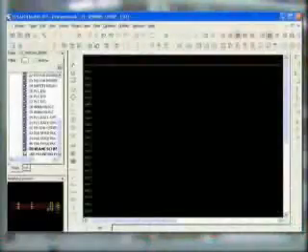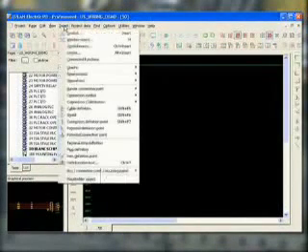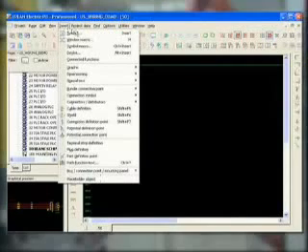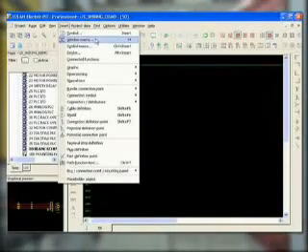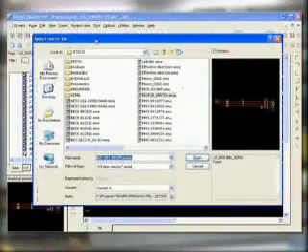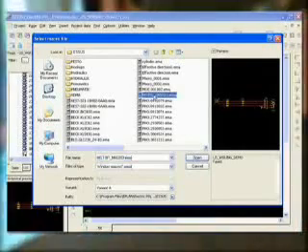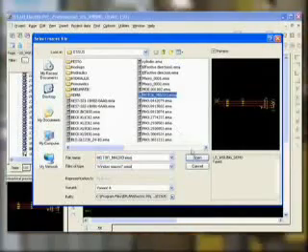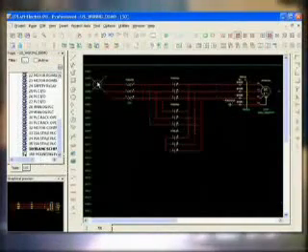When inserting a macro in Eplan Electric P8, a placeholder object can be used to access a table of pre-engineered data to assign to the components of the macro. To place a macro, select Insert and Window Macro. Select the macro to place. Variants can be accessed via the Tab key.